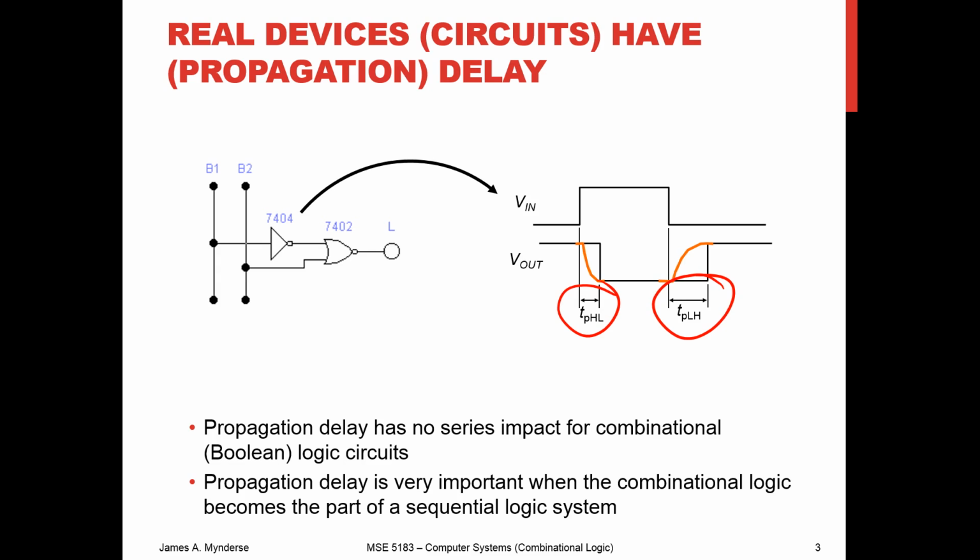So again, in combinational logic the glitch is short-term, and then you get the final answer. Sequential logic, it could screw things up pretty badly. So that's propagation delay. You have to be aware that it exists and plan for it. And remember that when we talked about our combinational logic and minimizing the mapping, we also talked about that we could deminimize in order to remove glitches that occurred due to propagation delay.